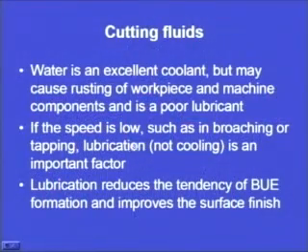If the speed is low, such as in broaching or tapping operations, lubrication is an important factor. Suppose we want to use water in operations like broaching and tapping, which are performed at a very low speed; we want lubrication to take place. Water may not be an appropriate cutting fluid in these cases, because water is a poor lubricant. So, we can't use water here in broaching and tapping. Here we will have to use a particular oil depending upon the workpiece material and the tool material that we are using. So, here the main requirement is lubrication, not cooling. If it were cooling, we would have directly used water.